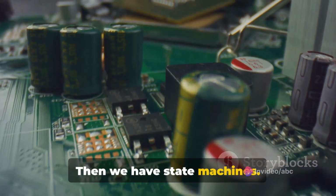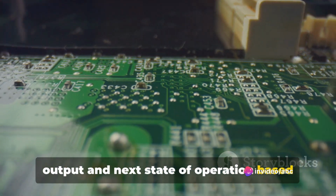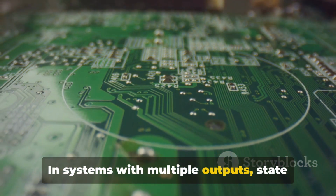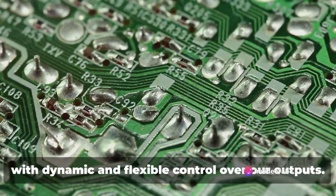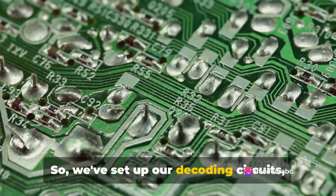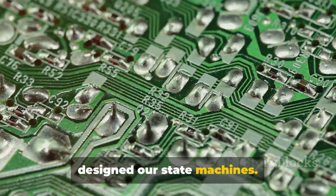Then we have state machines. These are devices that change their output and next state of operation based on the current input and state. In systems with multiple outputs, state machines are invaluable. They allow outputs to change based on the current state of the system, providing us with dynamic and flexible control over our outputs. So we've set up our decoding circuits, arranged our flip-flops and registers, and designed our state machines.